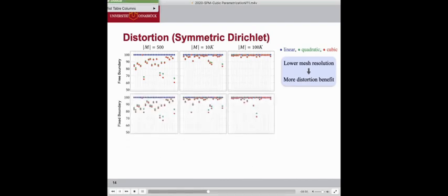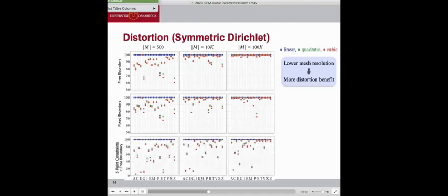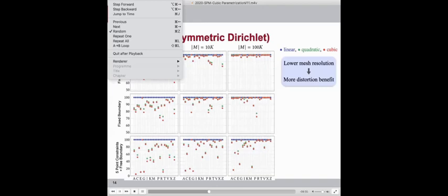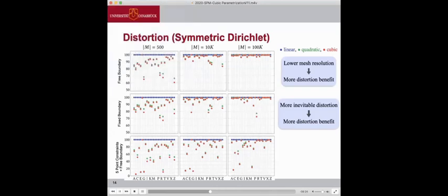We plot the same for fixed boundary and with 5 random point constraints to create scenarios with more inevitable distortion. Note that the distortion benefit is more significant the more distortion is inevitable due to constraints or surface curvature of the input mesh. And finally, we can see that the jump from linear to quadratic setting is quite high, but not as much for quadratic to cubic. So one should use either quadratic or cubic. Going beyond cubic commonly has a negligible effect.